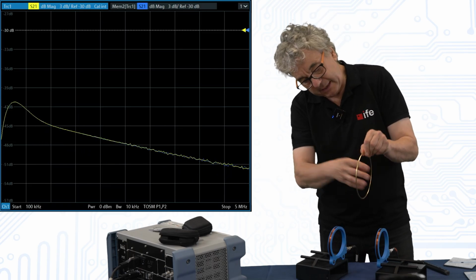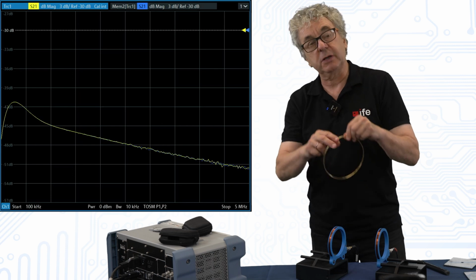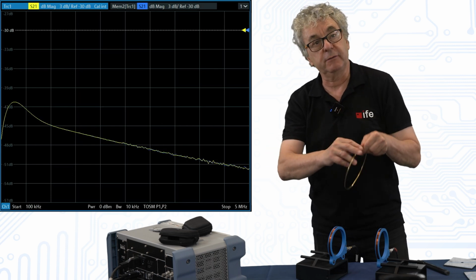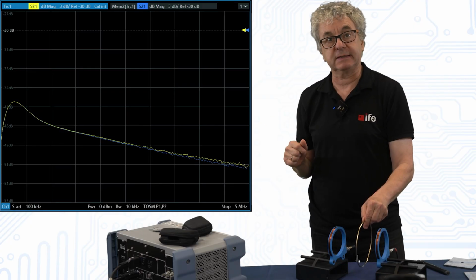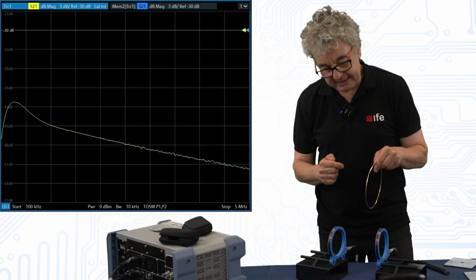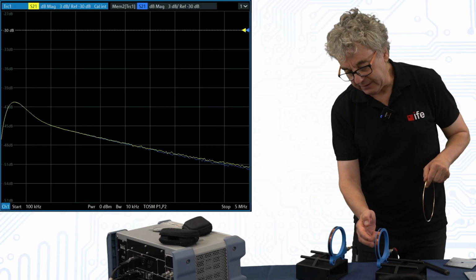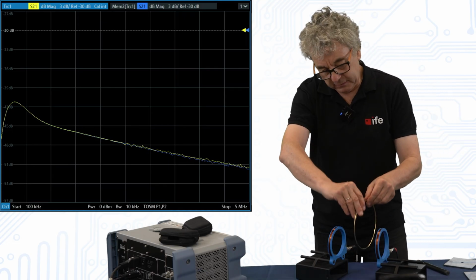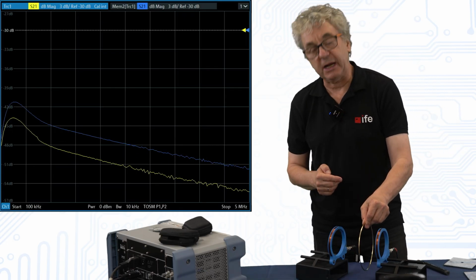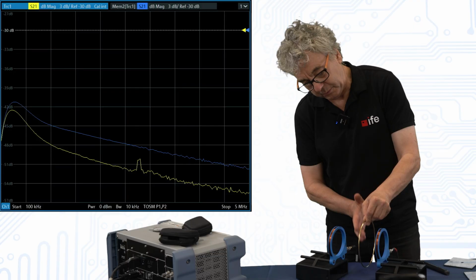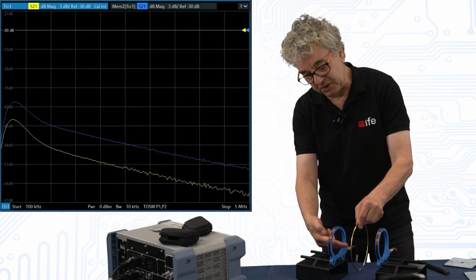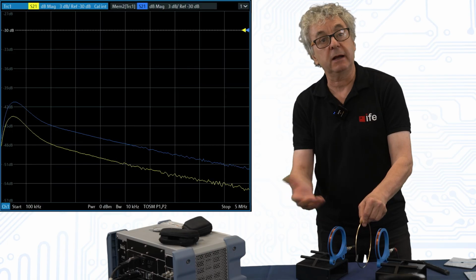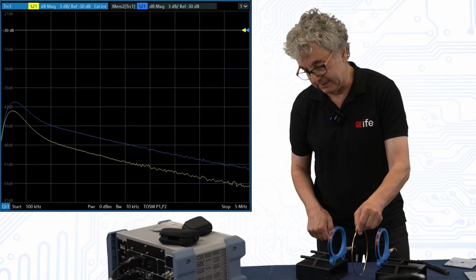The magnetic field penetrates here, induces the voltage, and if the gap is closed, a current can flow. And now we come back to the same concept we used in the other video. This coil receives the field from here, but if we put this in, there's a reaction field. The reaction field is caused by the current which is induced here, and now this coil sees both fields. It sees the initial field and the reaction field, and they are out of phase, so this reduces.